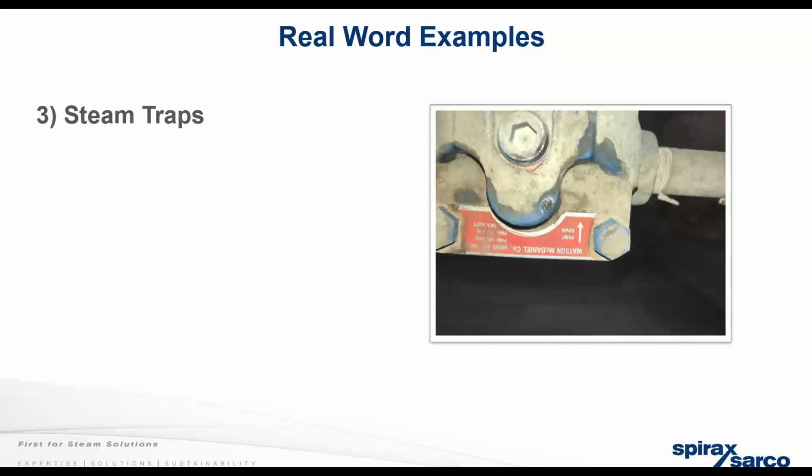Steam traps. There's a reason steam trap companies are still around today. There are what I consider 3 or 4 really major issues, but steam traps are a necessity. We need to install them correctly. This was at a site 10 minutes from my house. He said, I have a water hammer issue. The steam traps were installed upside down. Steam traps can also not work properly.